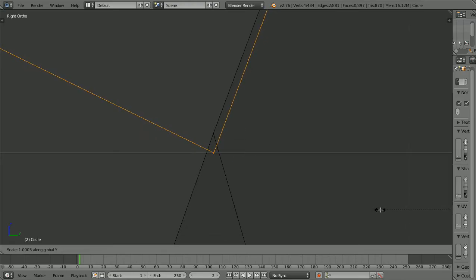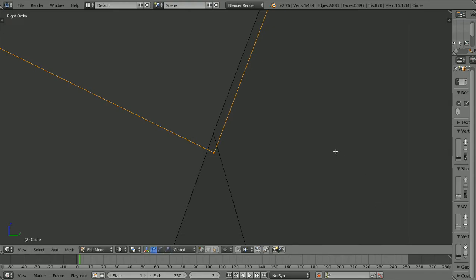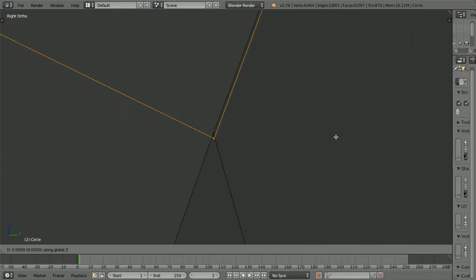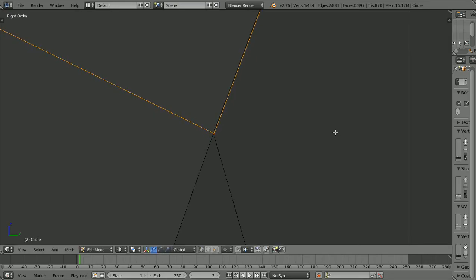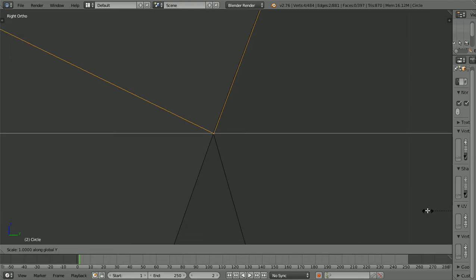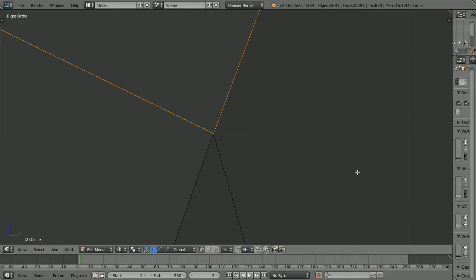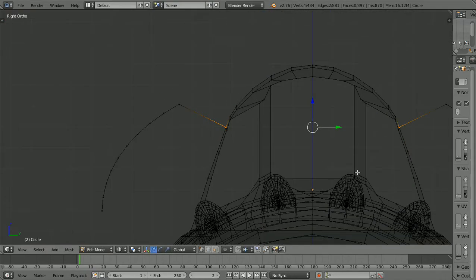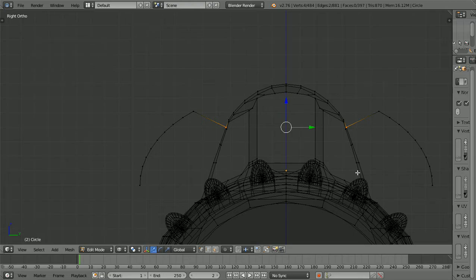But like I said, you've got to compromise, and that's why I like to learn tricks for how to do something where, let's see, grab it to the Z, where you can make it really accurate, but yet do it in a timely manner. Scale to the Y. Now, see, all you have to do is accidentally be tired, and when you should scale it, you grab it instead of scaling it. Grab to the Z. That's also where practice comes in, because that's the kind of stuff I used to do. I accidentally grabbed it and dragged it to the left, and since I have that other side selected, I'm dragging it the wrong direction.